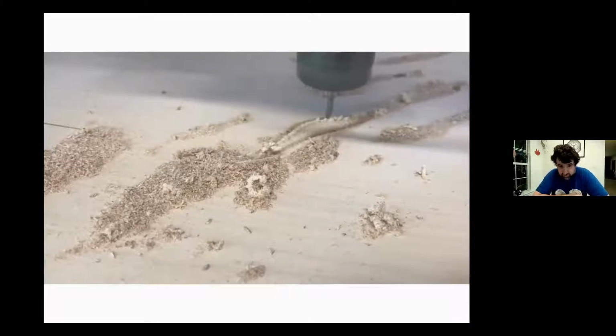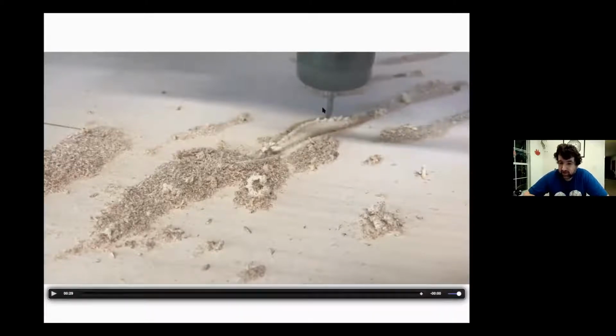3-axis CNC machine. And so as you can see, it's a spinning router. And now I'm going to try and do things with my hands. So you have this router spinning, and that router is on a gantry that can move up or down. You saw it in that video, the bit being moved up and down. That piece that goes up and down is then on a further thing that can move left and right. And then that whole system moving left and right is itself on a gantry that can move forward and back.